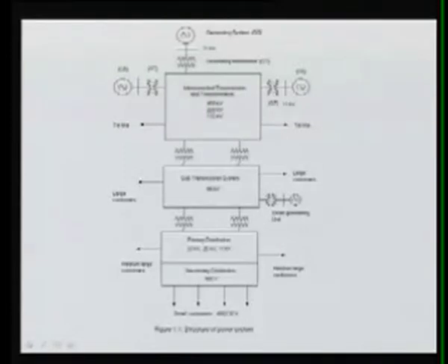So our intention is to keep increasing the voltage. Already I gave information about the evolution of the power system, where we saw the increase in voltage level in the transmission system. It is witnessed that we have to go for higher voltage transmission systems to reduce the loss and to transmit a bulk amount of power. So these generating stations generate power and then we use generating transformers, normally called GTs, very near to the generating stations.